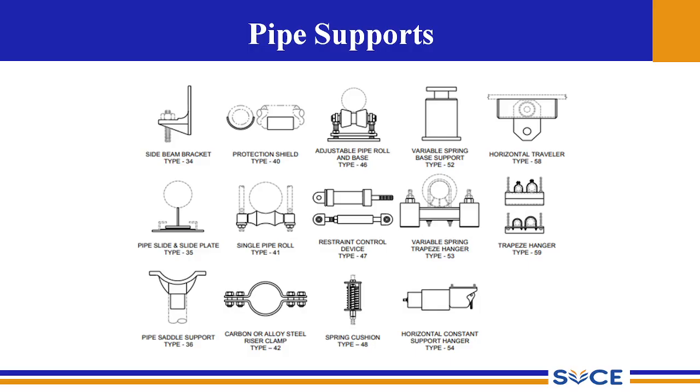So you can imagine it to be a structural type of rod hanger. If you do not have enough space to install any other kind of support, but there is some offset in the pipeline, we have to minimize the offset by installing this horizontal traveler where we have limited space.